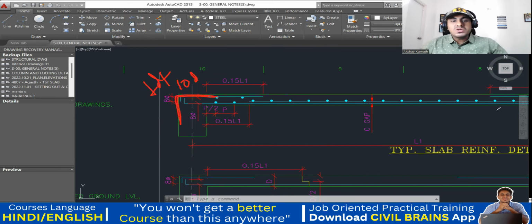So as a result of that, a huge bending moment will come. We don't want that to happen. So that is why we are giving only a small bend, only this much, only Ld, 8 times the diameter. Don't give it completely like this. Usually, practically on the site also, we do the same thing. This will be 8 times the diameter.